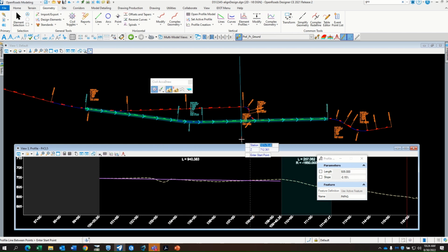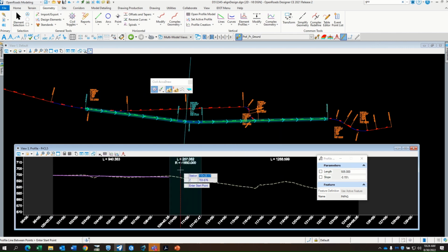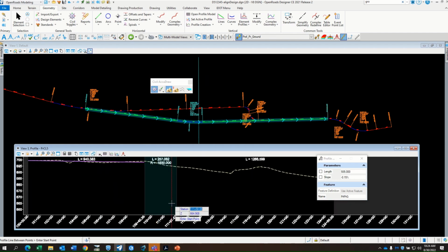So, since you're most likely beginners getting started, I would recommend probably turning that persist snaps off in the beginning. I often turn that off, and I leave links on, because sometimes you end up with results that you did not intend because you kind of forgot about the whole design intent thing. So it's nice that we do have the ability to turn that off.